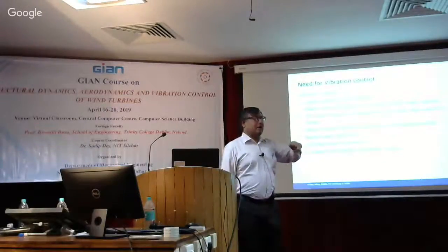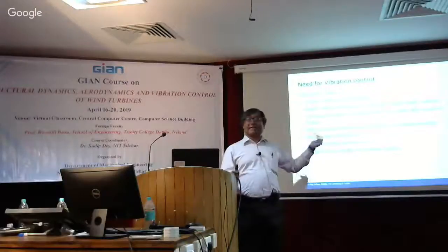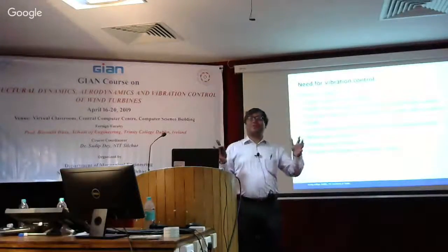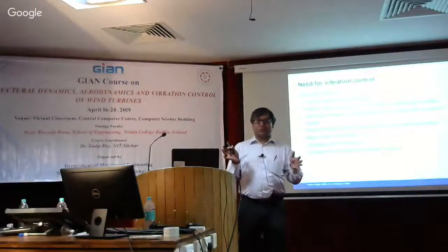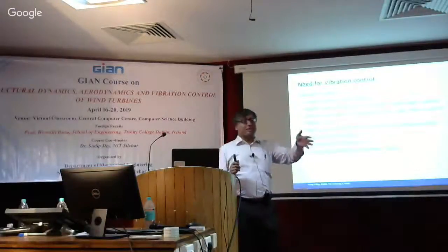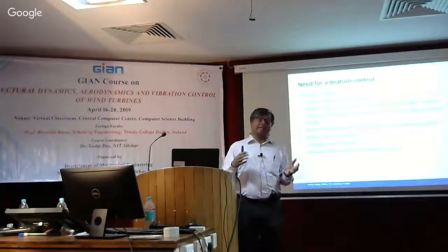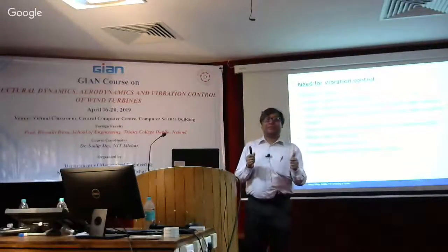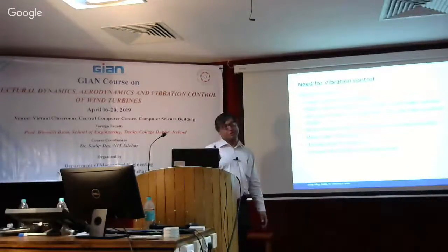And you've seen that the motion of the platform is roughly, in one of the cases, 30 seconds, half a minute was the period. So there's hardly any vibration control device available to control that kind of motion. So platform motion is almost impossible to control. So obviously the pitch controller can be used. They used it, but then the problem was it actually made the system worse. Whether because of some kind of base delay, time delay, it's not very well known. So it's still a big challenge. And the next major breakthrough will be when we can actually do something about this. Not with the conventional structure, probably more.